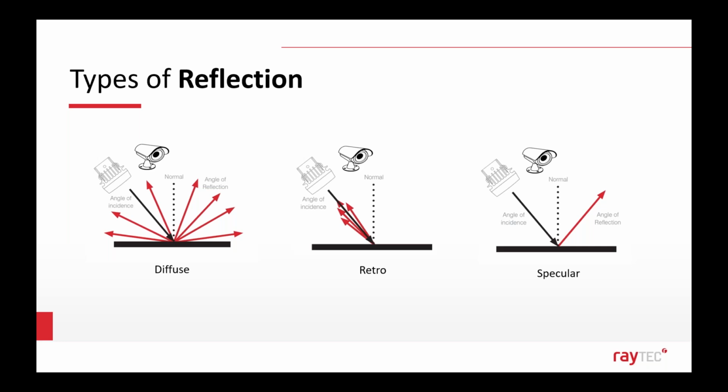Theoretically, the retroreflective license plates could also become specular too if you exceed that generally agreed maximum of 25 to 35 degrees angle away from the plate itself. More common than specular, though, is the man-made invention, and that's retroreflective.